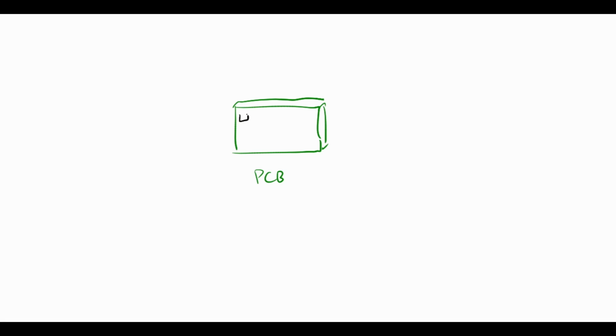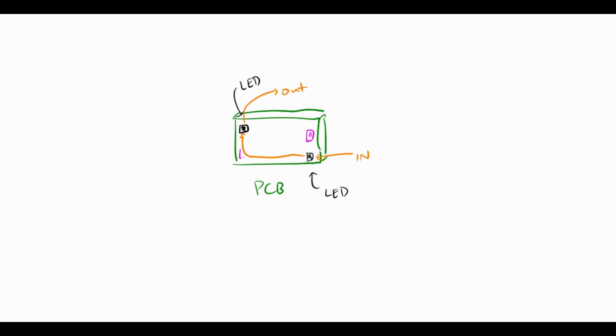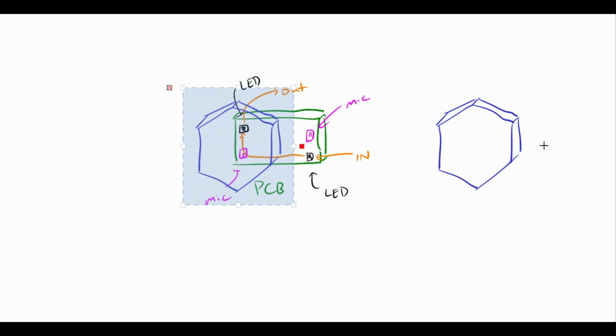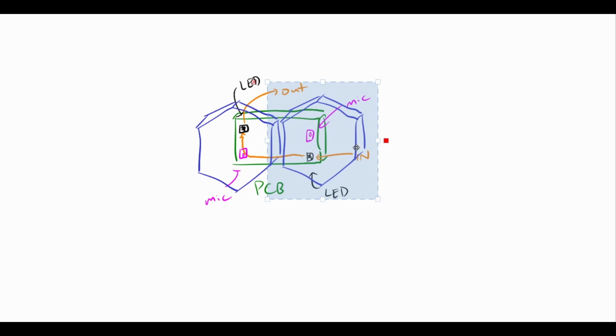Two LEDs will be implemented onto each board, with each board straddling between two tiles. This will save me from having to build twice as many boards. The LEDs are easy. There will just be a wire to the data input of the first LED, and a trace on the circuit board to forward that signal from the first LED onto the second. Each board will also contain two microphones, one to couple to each of the two tiles. But now I need something to monitor these microphones and report back the maximum voltage swing from them.